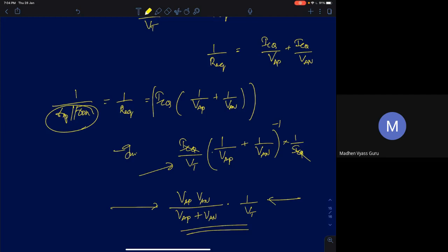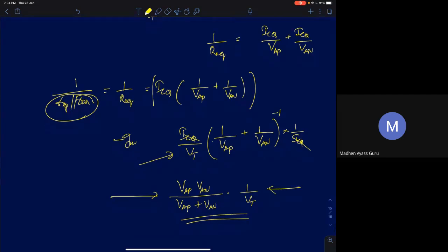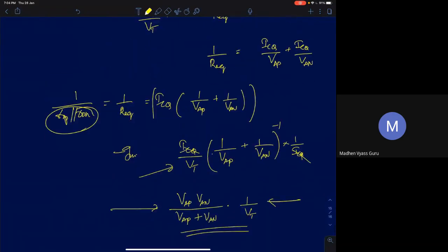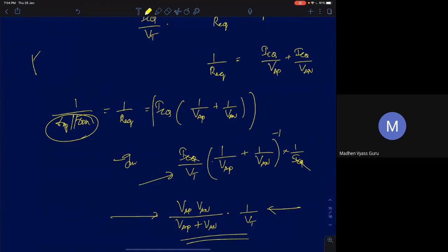Gain depends on bias current only in some specific examples. We took an example, right? I'll scroll it up. See, we took a specific example where we said, let's assume we have a circuit like this. This is Vi. In this circuit, we said the gain, if you assume R0 is infinity, I have given an example when R0 is infinity. In that specific example, the gain happens to be minus gm into RL.